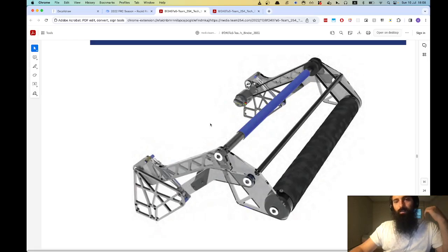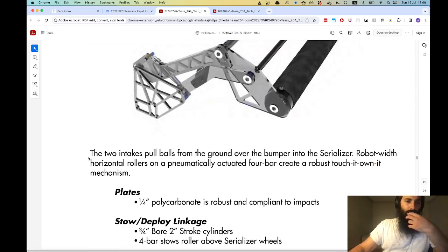So in our program, we can start to think of this intake as, well, there's a motor here, and a motor is an electrical component which we can direct in the code. All of this right here is mechanical, and the code won't know about these pieces of metal or all of this hardware. But what it does know is that in its world, there's a motor that can spin. And then you can see over here that there's a pneumatic piston, which is clamped down here and up here. When it extends outwards or inwards, it actuates this intake up and down.